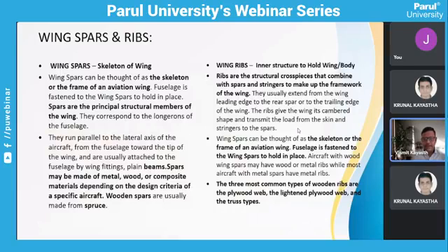Mainly they extend from the leading edge to the rear spar so that it could hold on for a longer period of time. Talking about the shape as well, it will be giving the shape of the airfoil that we have determined. Okay, and moreover, they will be covered with the skin or the upper foil that is going to be used to cover the wing.